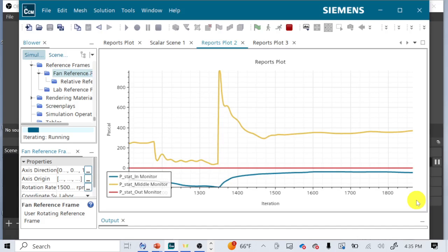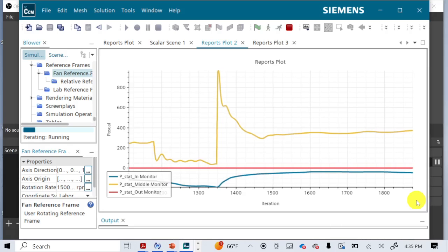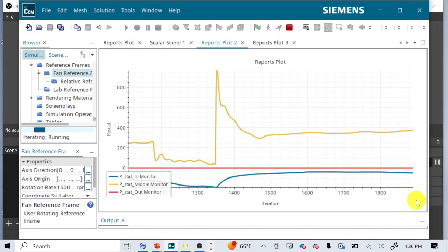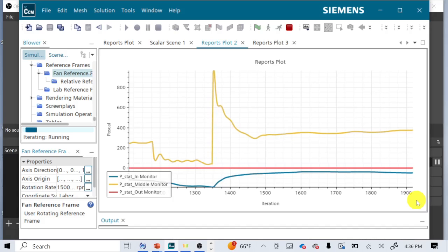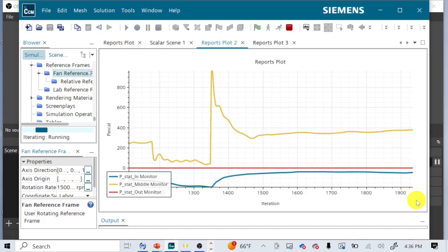So conceivably, temperature could be one of them. For lots of turbo machinery, temperature will change noticeably. Maybe not here, but that might be something worth validating. So we could also potentially look at mass flow rate. So mass flow rate, rho, and temperature could conceivably all change, although these are going to be less interesting than these three quantities. And that goes for pretty much anything unless you're doing a lot of compression, is that, well, theoretically, this should always be closely related to volumetric flow rate.